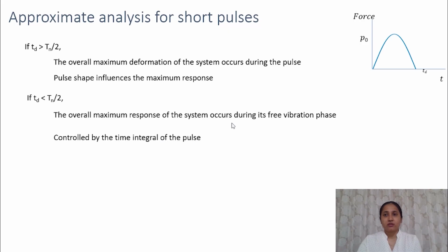and this response is controlled by the time integral of the pulse. So if the duration of the pulse is less, then the response is controlled by the area of the pulse, not the shape of the pulse. Area under this curve decides the response.